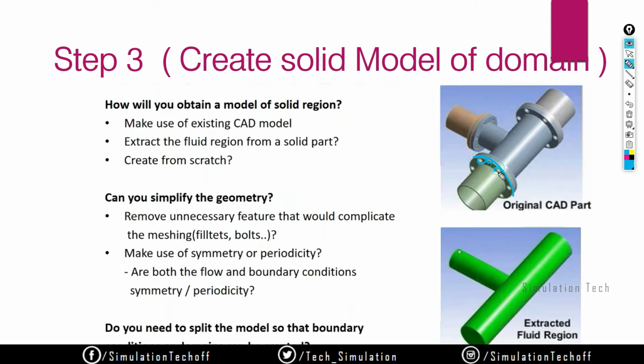We have a hole like this region, and we are only interested in the fluid region. So instead of creating the entire model, you can create or extract only the fluid region, because this is the region where we actually do the analysis. For a simple model, it will be very easy to extract. For a complicated model, you need to think about where the analysis actually takes place. We don't design the entire CAD model for a CFD analysis; we only design the fluid region, the domain in which the fluid analysis takes place. That is what you need to do here. I just modeled the fluid region in this CAD model.